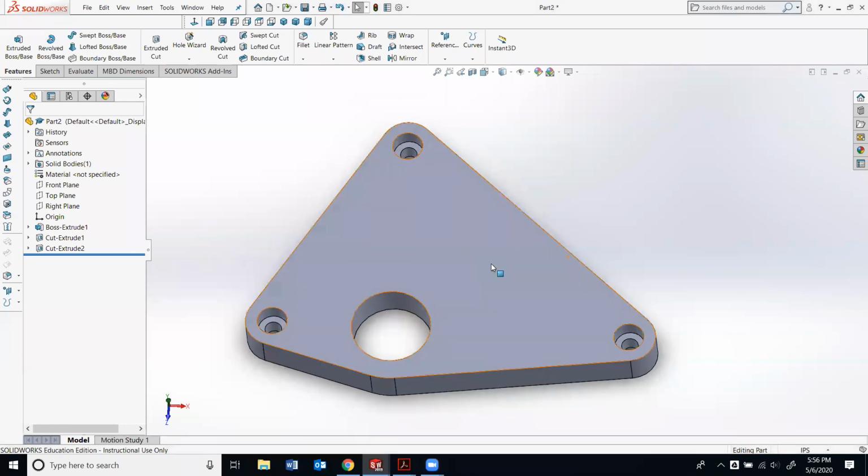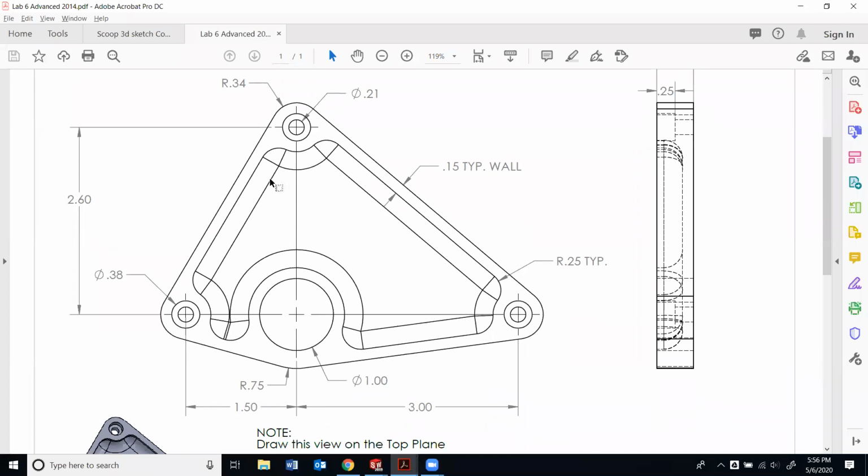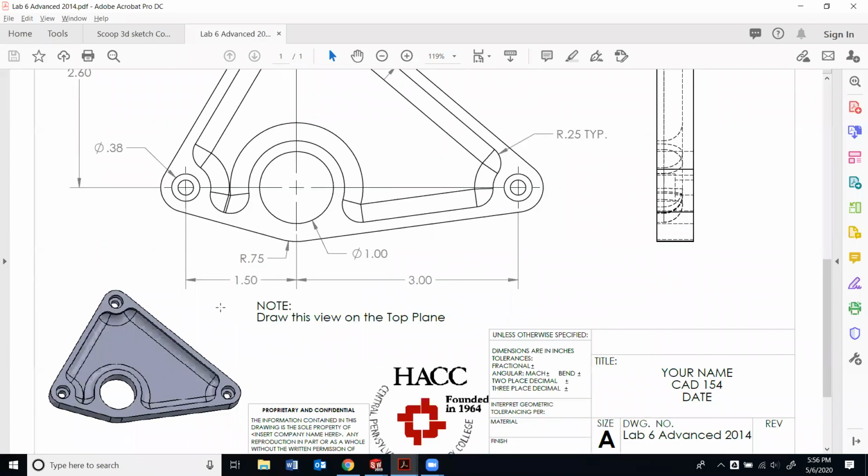All right, so the next thing we want to do, if we look at here, is you got this weird shape here, and it's kind of confusing, but all it is we shell it out, and then we use the fillet to round the corners, okay? Because if you were popping this out of a mold, you can't pop it out of a mold with straight corners. It won't come out. So you need to round the corners, fillet them.